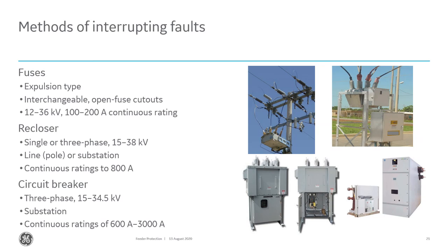Reclosers we talked about. They could be single phase or three phase reclosers. Most of the time you'll see the reclosers on overhead portions of the distribution line on pole top, but that's not to say that there are cases where they might be in underground sections on pad mounts, or they could be at the transformer at the substation on pad mounts.